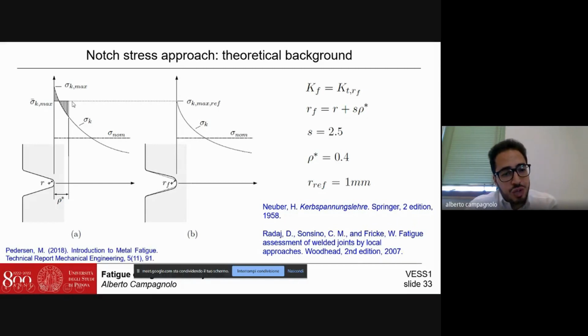However, the averaging procedure is not easy for typical notched structures, so Neuber also proposed a different procedure to calculate this average stress, which was to define a fictitiously rounded notch which has a modified notch tip radius as compared to the actual original one.